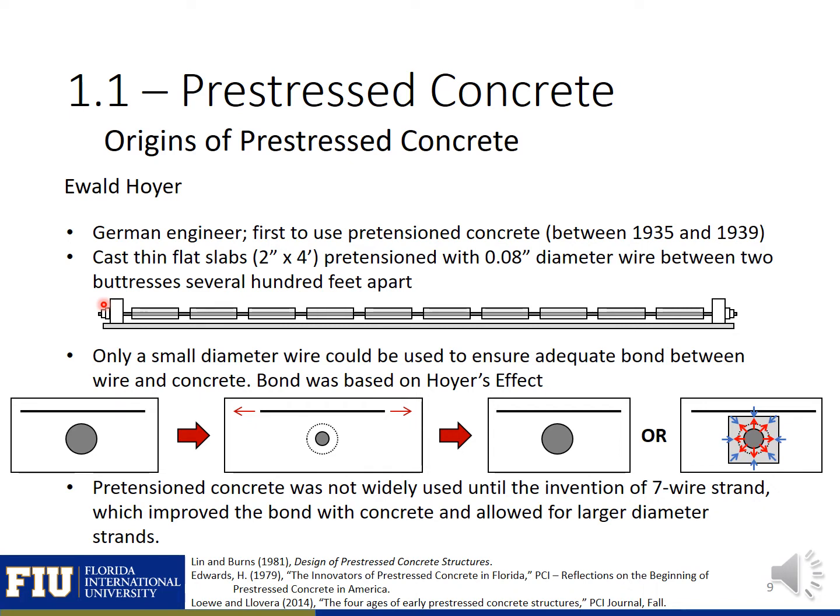Because there was no end anchorage to transfer the stress from the anchorage device to the concrete, the transfer had to occur between the wire and the concrete itself. And this is when Hoyer discovered what has now become known as Hoyer's effect.